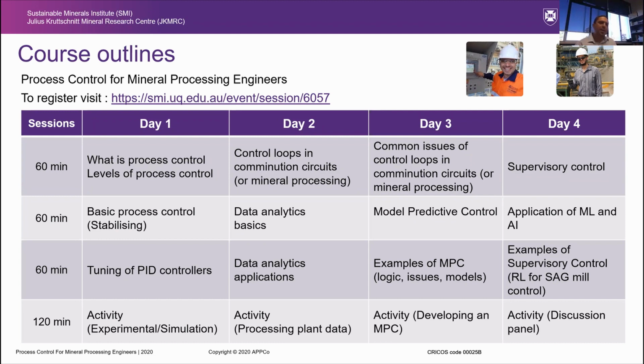One of the examples is our mill filling prediction tool, which essentially uses our power draw model and the mill load measurement model that we have, which uses the power draw measurement, which normally can be done reliably in an operating plant, and the mill load measurements that are often done by load cell or the lubrication pressure, or turning pressure, and then uses that to infer the total filling and ball filling, which is very hard to measure.